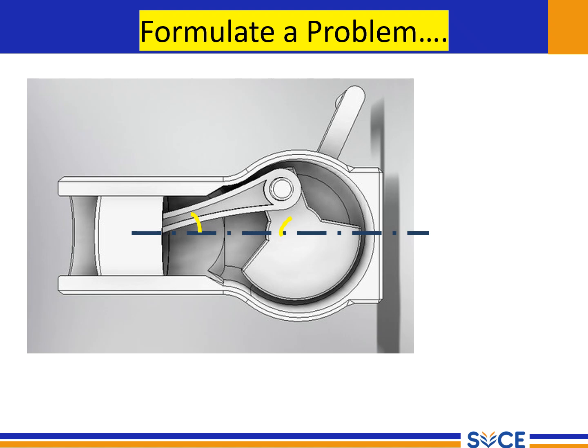So in our force analysis, we generally follow these steps: determining the gas force which is acting on the piston, so it is your FP. Then calculate the inertia force of the reciprocating parts. Then determine the piston effort. Then the fourth step is calculating the force transmitted to the connecting rod. Then determine the crank pin effort, that is your FT. Then determine the bearing load, turning moment, all those things.